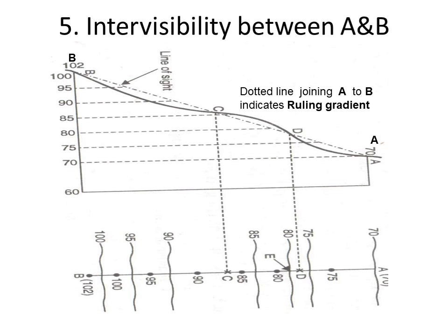We are supposed to draw the cross section as explained earlier, considering the horizontal equivalent and the value of the contour interval. The values of the contour intervals are plotted on the y-axis, whereas the values of the horizontal equivalent are plotted on the x-axis, and accordingly,